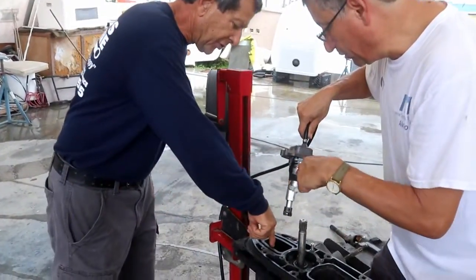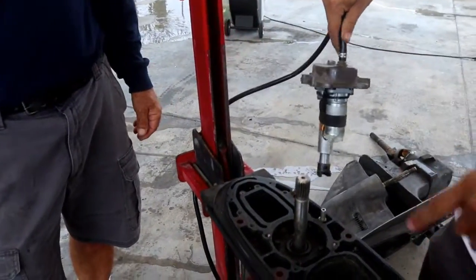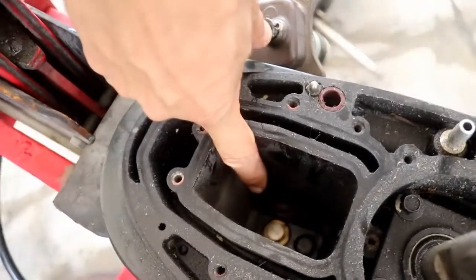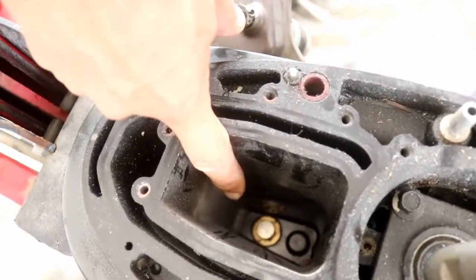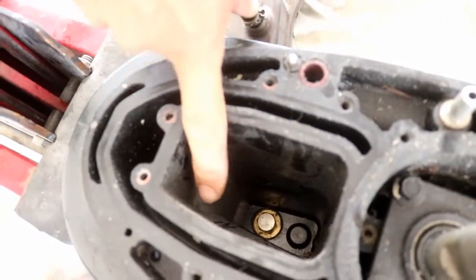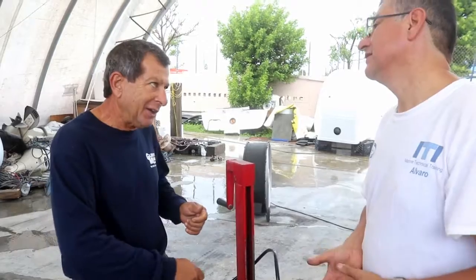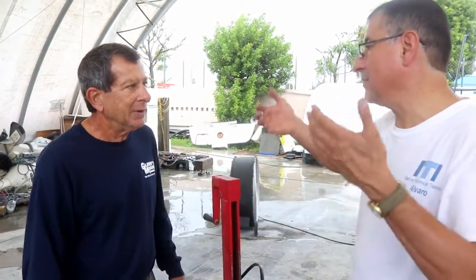And this one should be calibrated with this bolt, the bolt that you have on top. Okay, perfect. That bolt should be calibrated up and down. There's a gauge you set on top of this, and then you know if you got it right. If not, you take it out again, adjust again. Of course, you need to remove the lower unit to calibrate that.